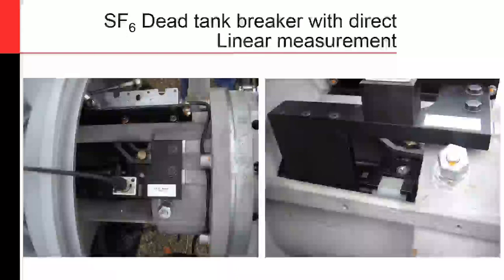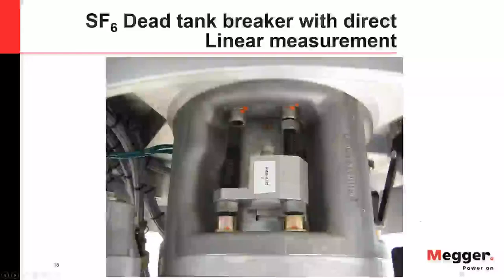I had mentioned that we have some special circuit breakers, or mechanisms really, where you have to hook up a transducer that fits directly inside of that mechanism. So this is one of those. This is the ABB AHMA, and then following that, we have the ABB AHMB. And so these hook up, and that actual mechanism is connected directly to the interrupter.